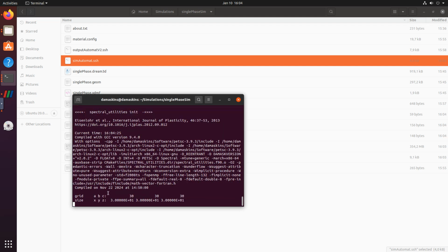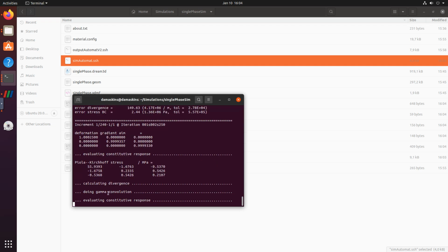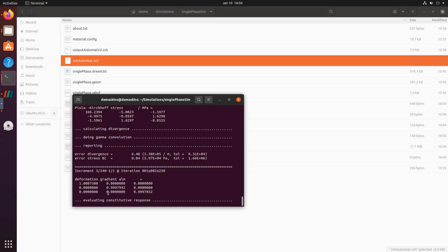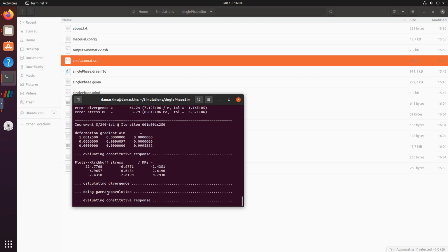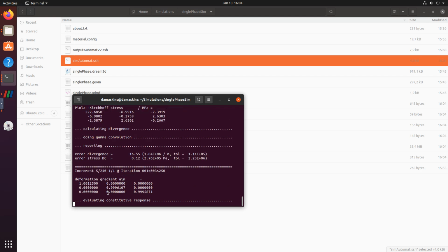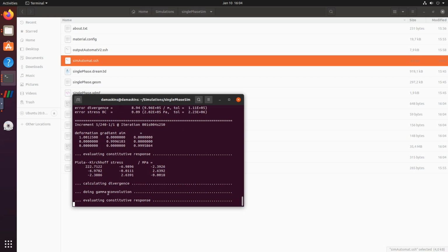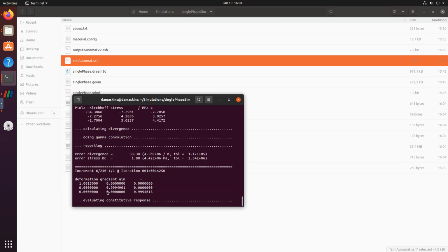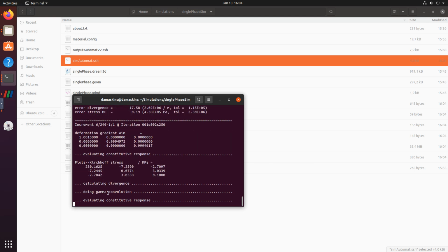And then now it will run the same simulation again, but now because the default number of processors the computer uses is 2, and now we have manually selected it to be 8, hopefully the simulations will run a little bit faster, and once the simulations are complete, we will automatically be able to post process our results globally and locally, and then we will see the results.